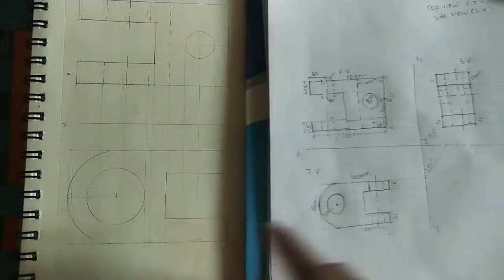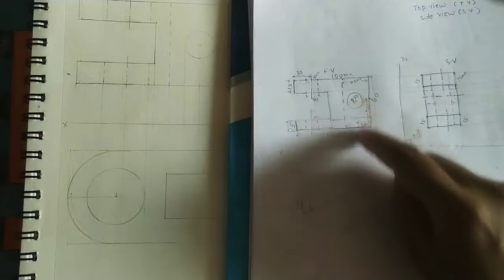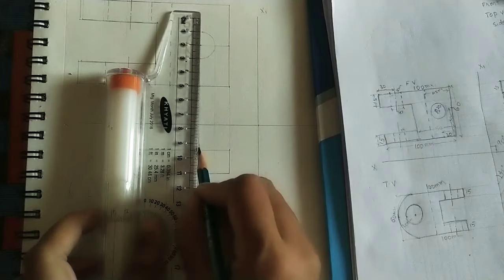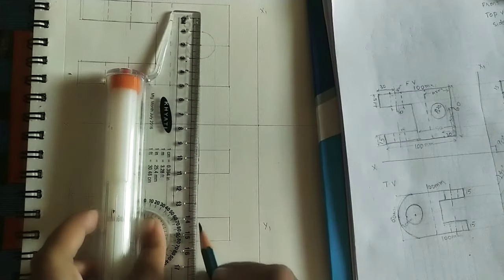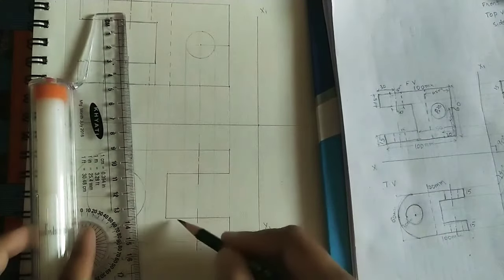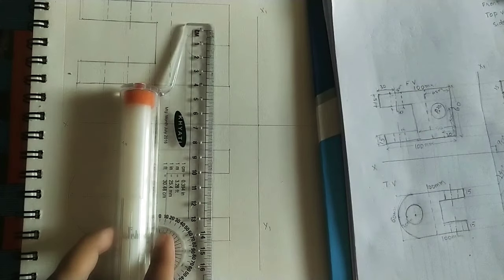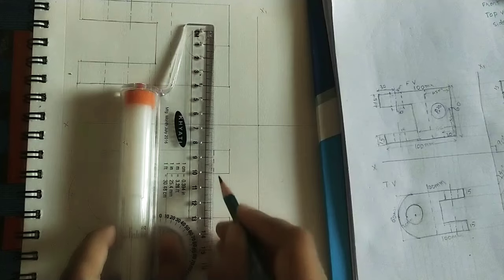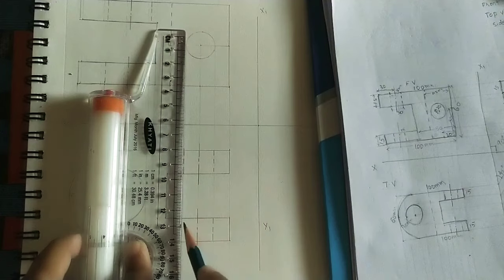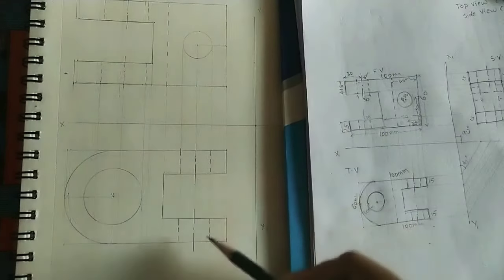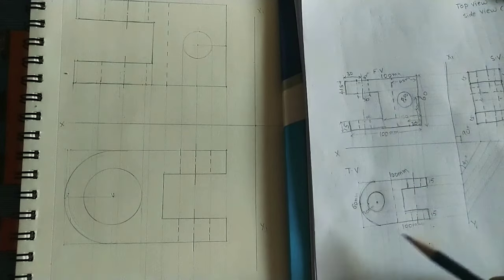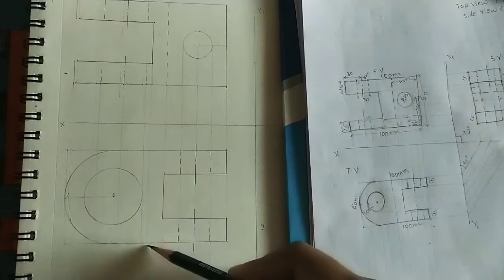After getting this circle, do the axis line. Take the center projectile line, and on it do the axis line on this side and this side. Axis line means two big lines with a dot. Here also. Now wherever these projectile lines are coming, here do the dotted line, on both sides. After getting these holes, wherever the projectile line is coming from the U section, there do the dotted line. Throughout the length, do the dotted line.